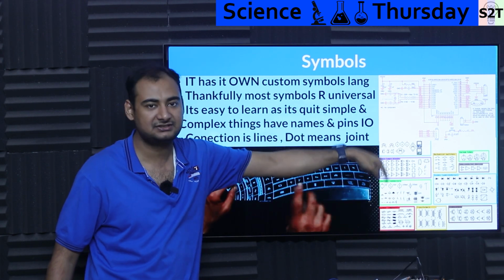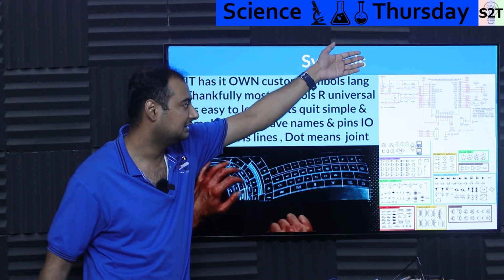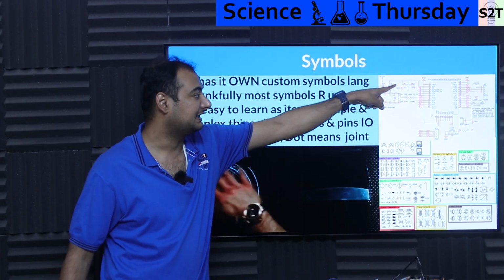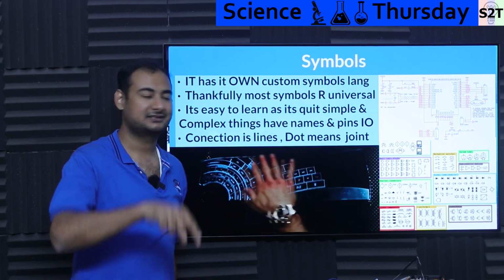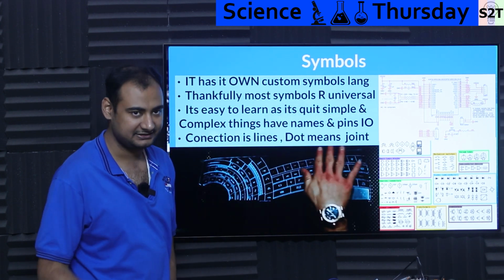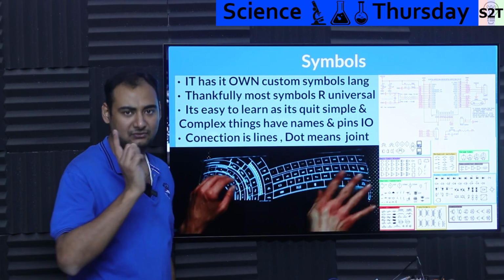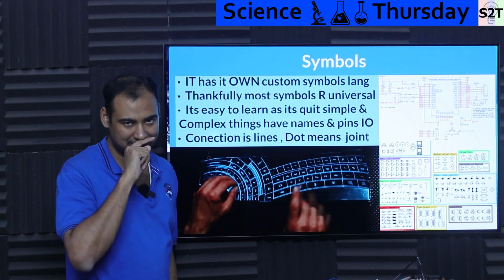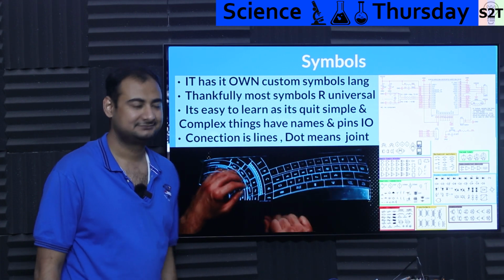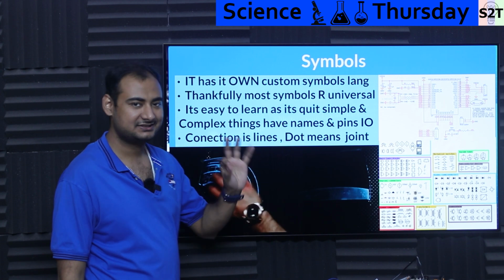It goes through pins 3 to 14, it just goes through. Is it shorting all of them? No, hell no, it's not even touching them. How do I know? Well, there are no dots there. Wherever you see ground and you see a dot, that means it's connecting. You see a capacitor dot, it's connecting. That's how we figure it out. It's an almost universal language in almost all schematics. If a line is crossing and there's no giant circular dot, that means it's not touching. If it has dots, it means it's an electrical connection.